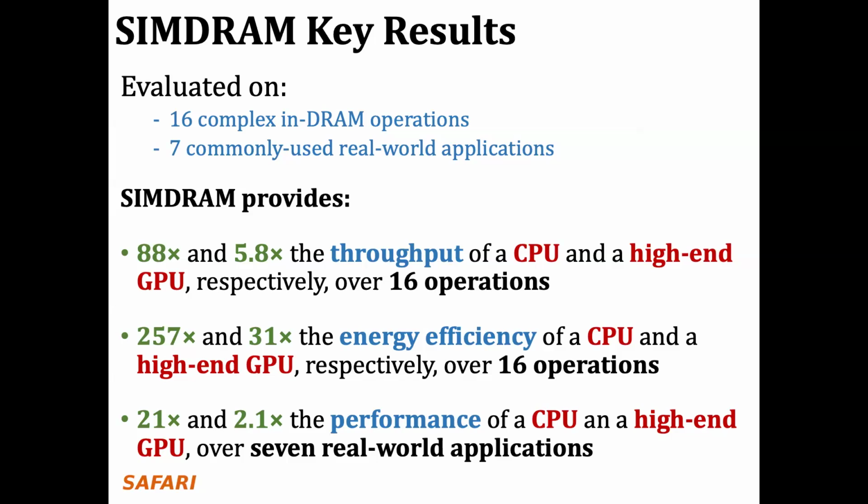Yes. Question. So there seems to be a locality issue. You have to make sure that in a system with a lot of DRAM banks that you basically are operating within a single chip. Yes. And absolutely, so you'd have some pragma or some directive. The OS has to cooperate too, because with virtual memory, you can't really guarantee that. Yeah, absolutely. Basically, you need mechanisms to map the data appropriately, such that the data that you need to operate on is in the same bank. Yes. Or you move it with the mechanisms that we did, like the row clone type of mechanisms from bank to bank, etc. Okay, thank you.